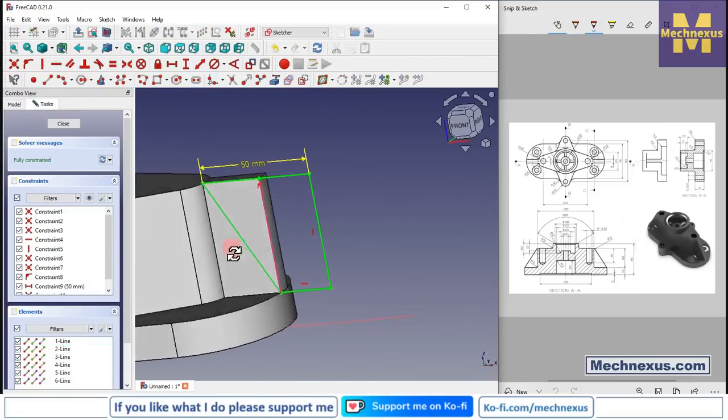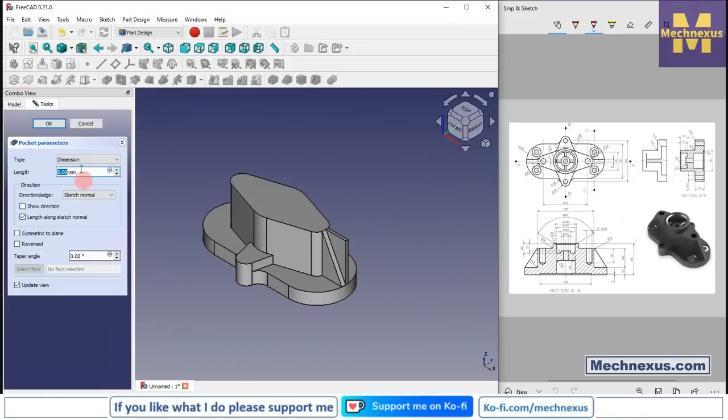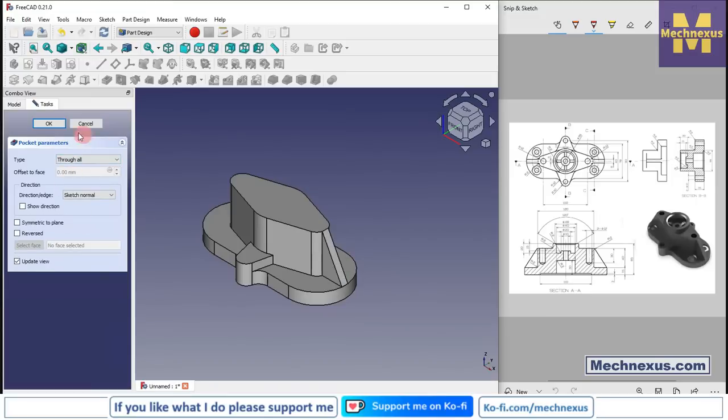So we have a fully constrained sketch and we will close it, select the sketch and click on extrude cut, and from here we will say through all, say OK.